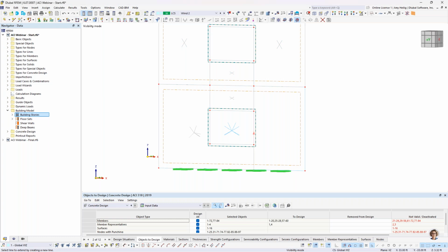And I'm going to do so here at the bottom right and at the bottom left. And now you can see that those line elements are automatically created again without affecting that opening. And the surface cells were automatically detected when we do this. So in case you have a shear wall with openings, you certainly want to take this workflow.